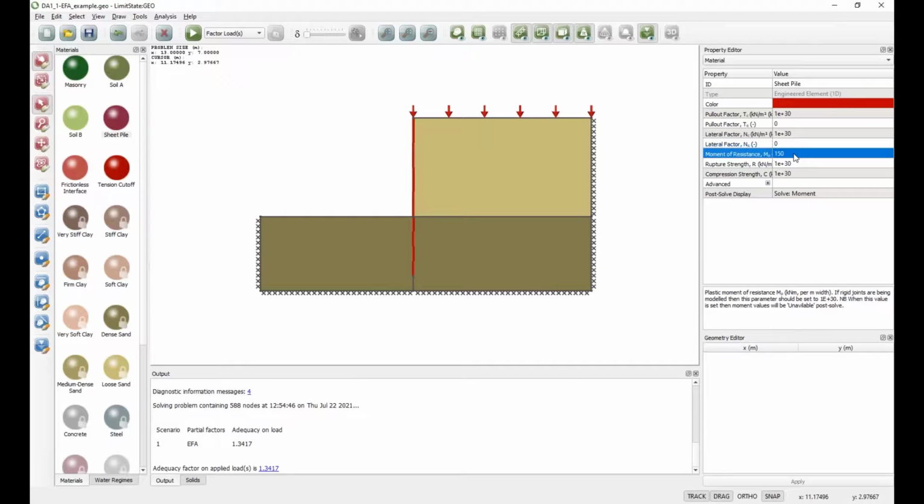And then that would tell us that's the strength of the wall that we need to comply with the code. And we would then multiply that by 1.35 to get the actual required value for our final design. I won't do that now because of lack of time, but it turns out to be 85. And if we multiply that by 1.35, we get 115 as our required value.